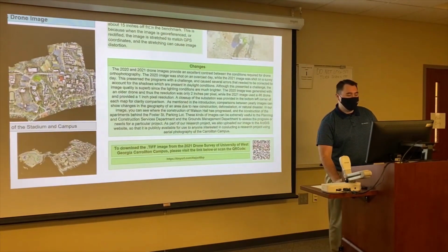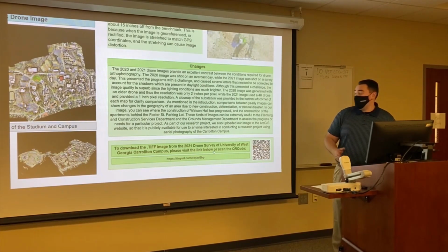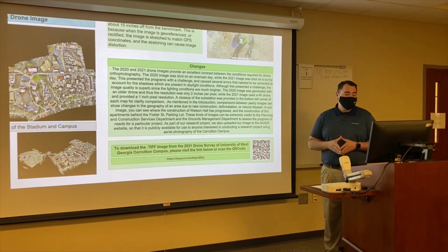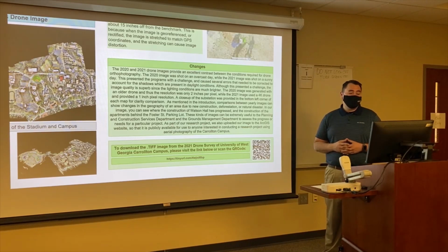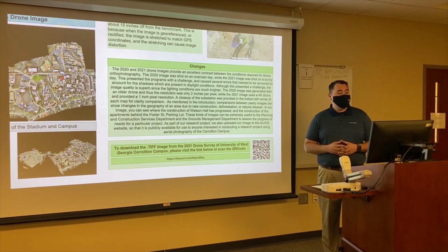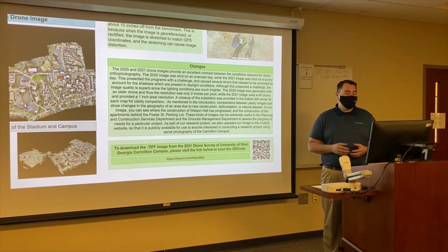Hello, my name is Bryant Burrow. I'm with the Geography Department at the University of West Georgia. I'm going to talk about some changes between the two images. The 2020 and 2021 drone images provide an excellent contrast between the conditions required for drone orthophotography. The 2020 image was shot on an overcast day, while the 2021 image was shot on a sunny day.